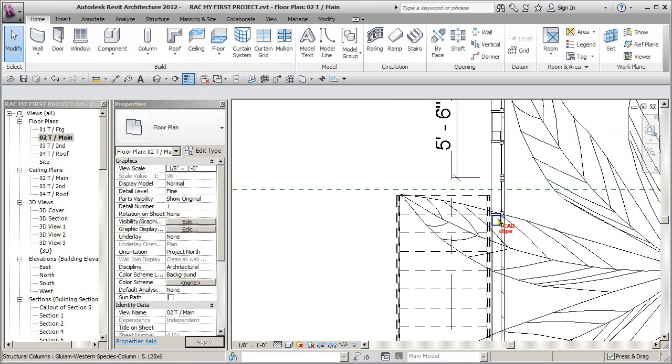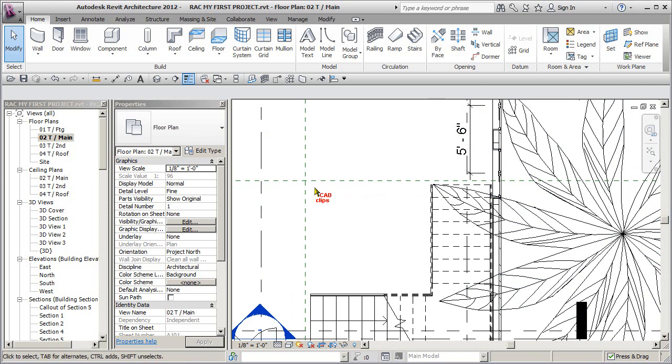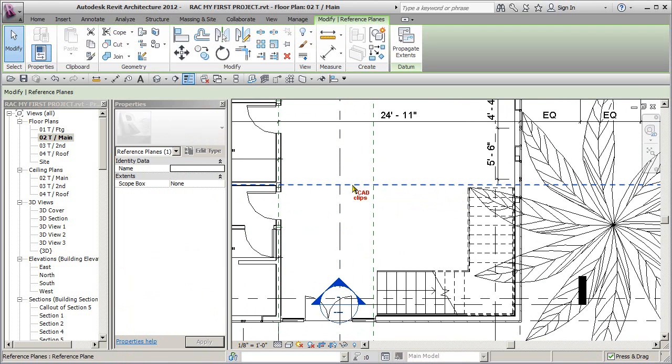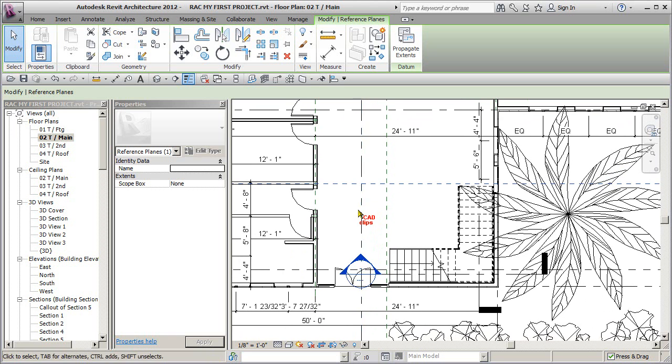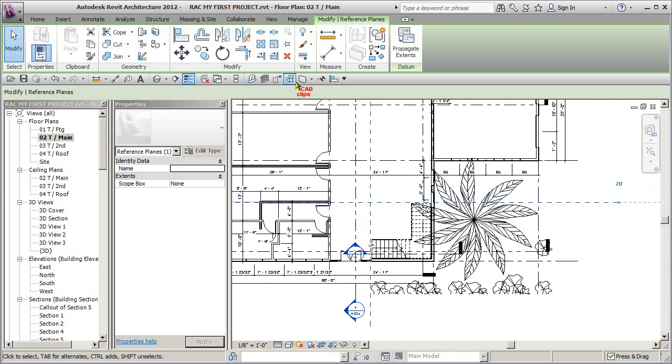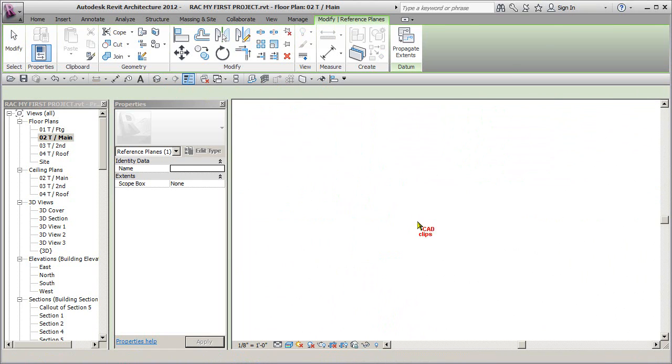Okay, and that's on a load-bearing wall. And we could put a detail line in here saying header over window, etc., because that's not really carrying a lot of load, because the joists are spanning this way, and there's your transfer point there, and that's being distributed across from there to there and then down these windows. So because the joist span is going this way instead of this way, there's not a whole lot of load going in there. But we've got those columns, and now we have our beams in there.